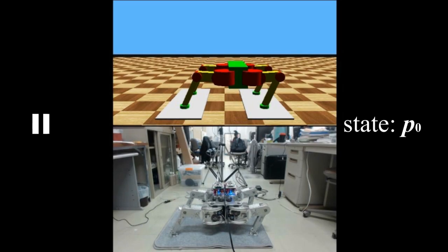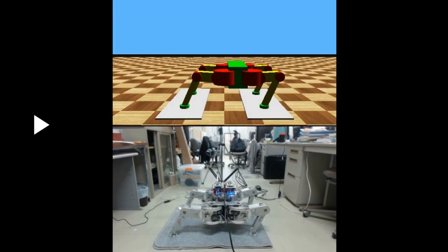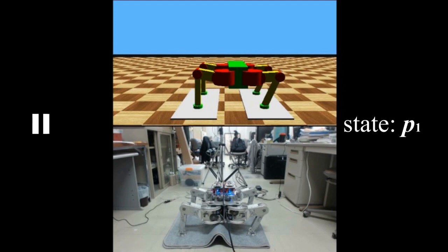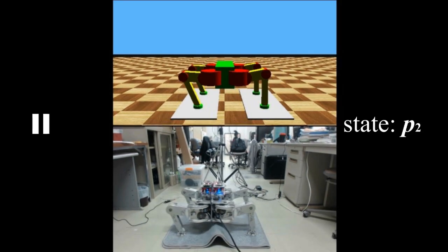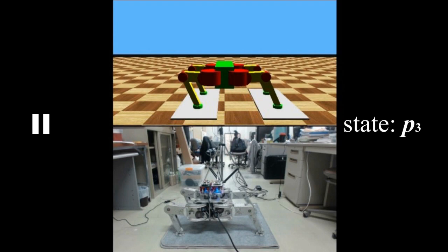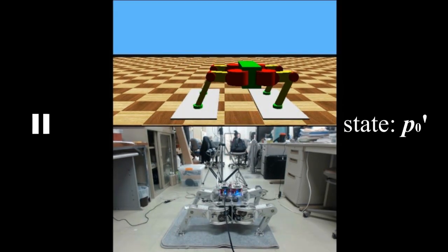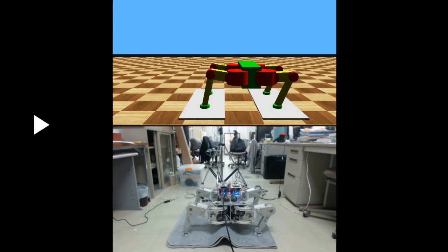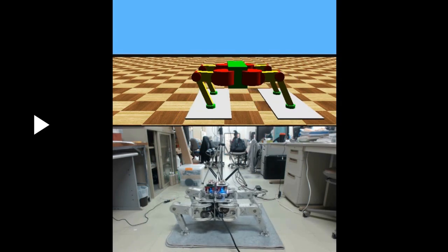In inchworm mode, all four feet of the robot are placed on the mat. The robot adducts its hind legs to create a bulge in the mat, and then abducts its front legs to flatten the mat, making the mat move forward in a manner similar to the gait of inchworms.